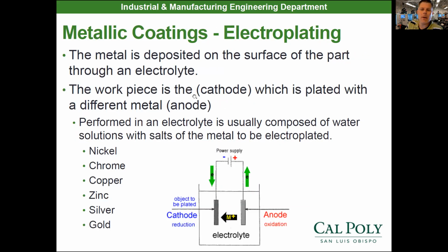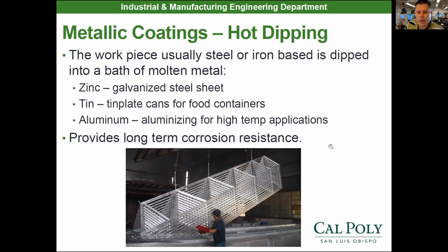So you have a full metal coating on the outside surface of your part. It's fully plated. There should be no gaps in there. It's down to the base metal. Now, if you've ever heard of galvanic corrosion, it means you have two dissimilar metals in the galvanic series, and one starts to corrode a lot quicker than the other. Hence, that's why they have sacrificial anodes, like on the bottom of boats. They have zinc sacrificial anodes.